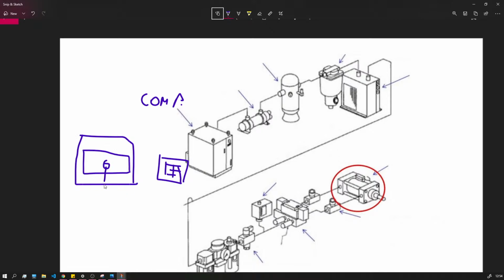There's a piston that moves up and down on the crank, and instead of, for example in gasoline engines, 4 strokes of movement, here we have basically two strokes. When the piston is moving down, it's opening a valve that brings air into the compressor chamber. The compressor actually compresses air.